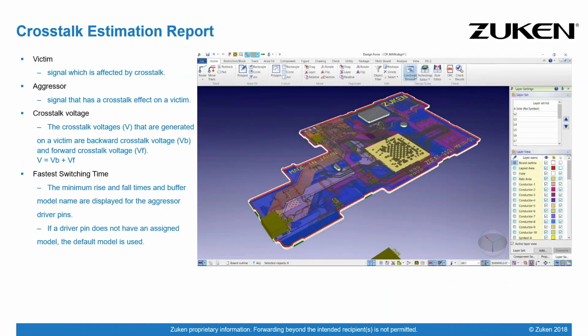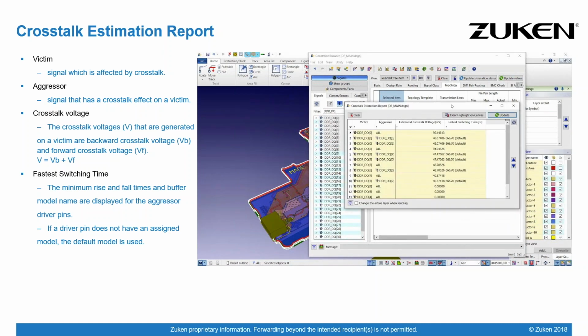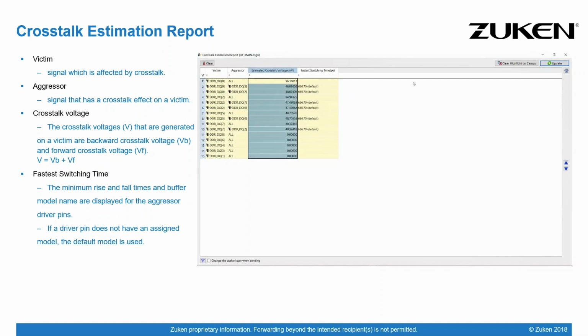One of the major issues in the high-speed design world is called crosstalk. And when you talk about crosstalk, if it's DDR5, it's more serious. Crosstalk is an unintentional electromagnetic coupling between the traces on a printed circuit board. For instance, if you have multiple signal vias in your DDR5 layout, and you have DQ0, DQ1, DQ2, maybe DQ3 and 4, all sharing one ground via, and they are coming back in the same localized area, that's going to cause your crosstalk.